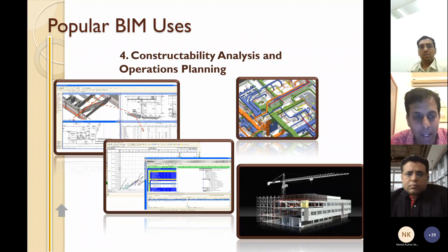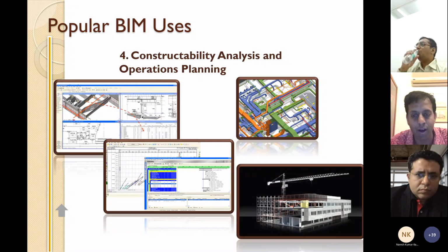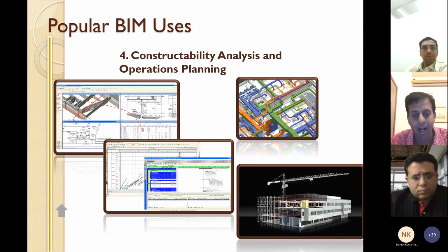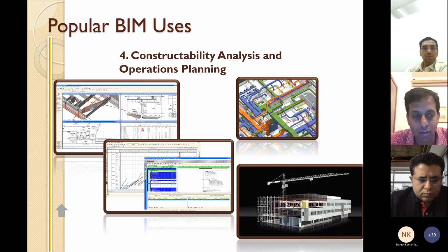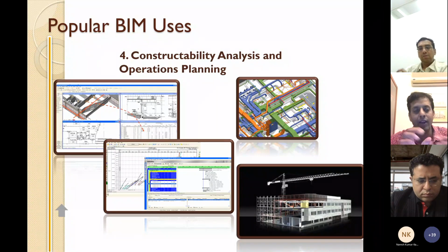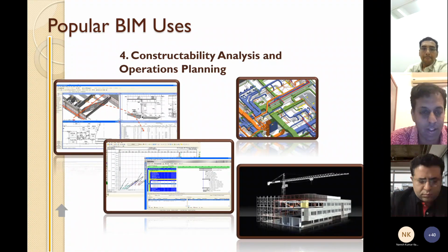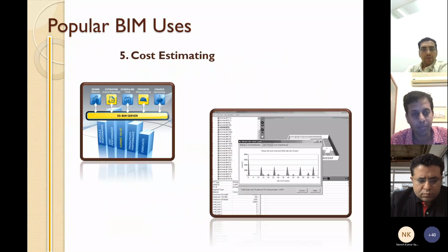Post design, BIM can add a lot of value in terms of being able to help you sequence the planning of the construction. So very often there are certain configurations of plans that might be inefficient, might lead to too many crews working at the same spot and therefore reducing productivity and so on. And you can therefore develop simulations using BIM, 4D simulations as we call them, to understand what would be the best construction sequence, and then implement a construction sequence that gets done as quickly as possible and therefore adds value.